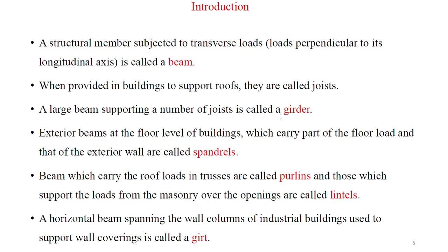Exterior beams have various names. The exterior beams at the floor level of buildings, which carry part of the floor loads as well as the exterior wall load, the load due to the wall, are called spandrels. Those types of beams we call spandrels.